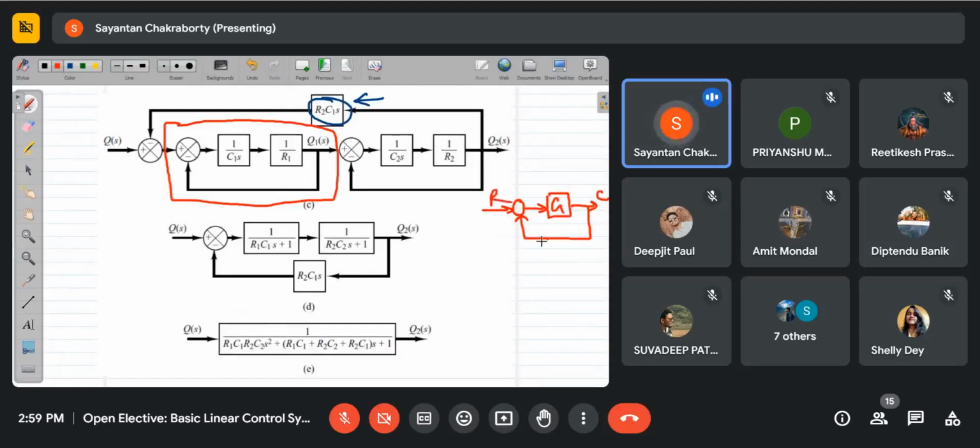It is G by 1 plus G. If we simplify that, I'll get this over here. And for this loop, if we simplify that, I'll get this. So this is the cascade part that is normally expected. But due to the interaction between them, there will be this additional part.